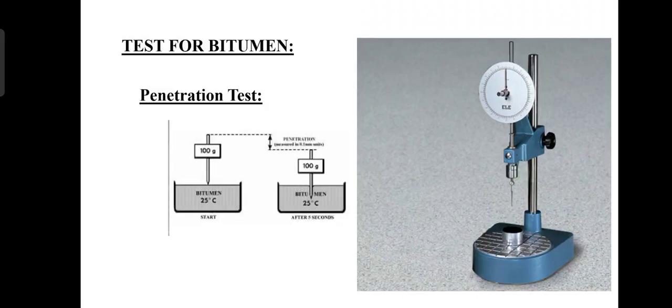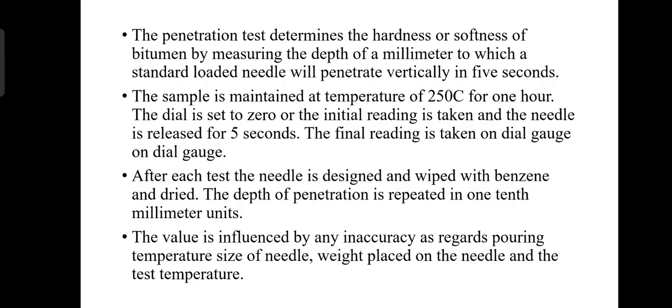So today we are going to see about the testers for bitumen. First of all, we see about the penetration test. In the figure you can see the penetrometer which is being used for testing the bitumen. So the penetration test determines the hardness or the softness of the bitumen by measuring the depth in millimeters